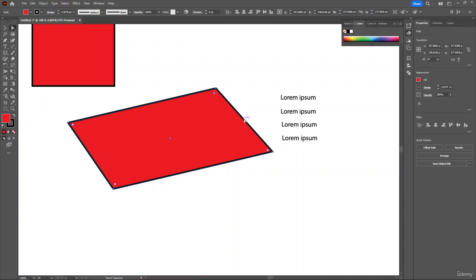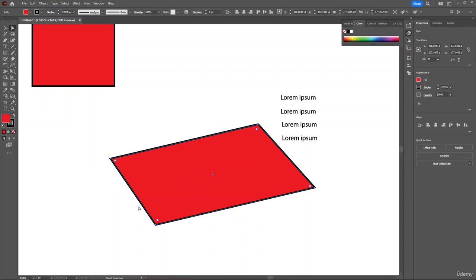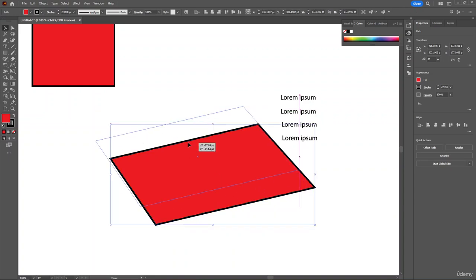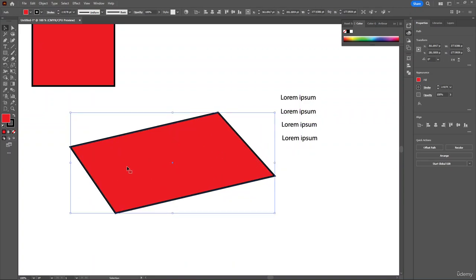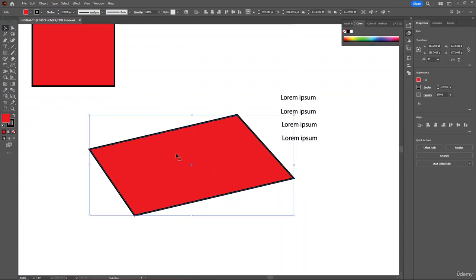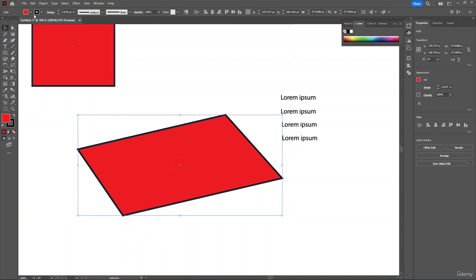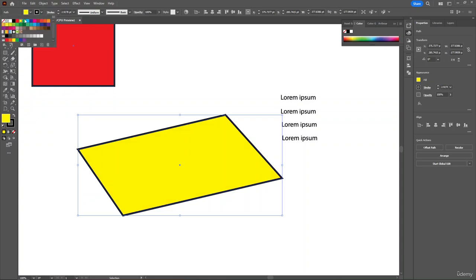Now that I'm done with that part, let's move on. Now I'll show you how to use the selection tool again. Below the menu bar, you can see that we have a path over here, which is basically our object type that we have selected using our selection tool. What I'll do now is show you how to use this whole set of tools. If I hover my mouse over here, you can see it's the color fill option. We can choose the color of our object from here.